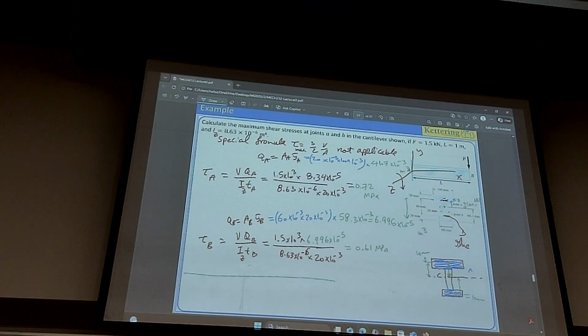Again, suppose the glue that you bought from that shop or store has a strength of, let's say, 1 megapascal. Then both A and B are safe. The strength should be more than the stresses that you're calculating. You did the calculations so quick and precise.